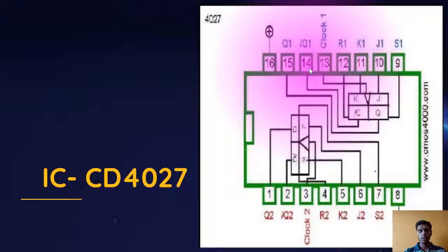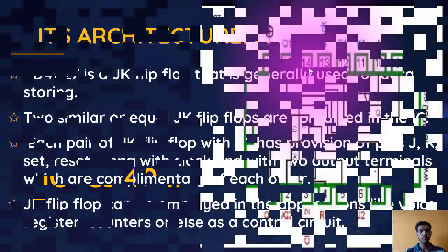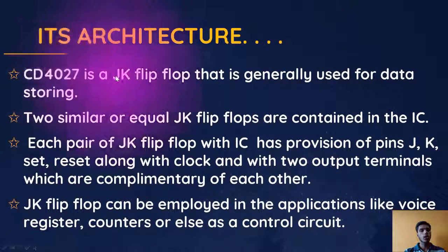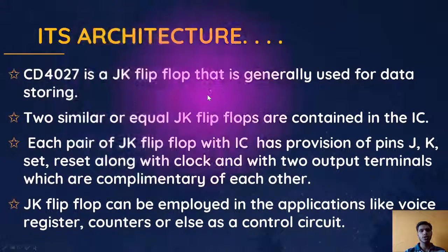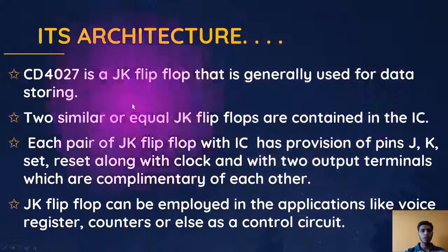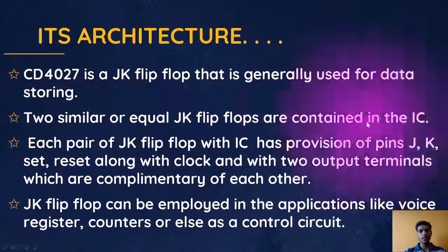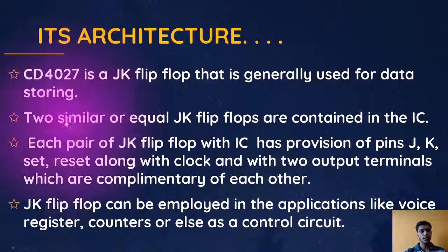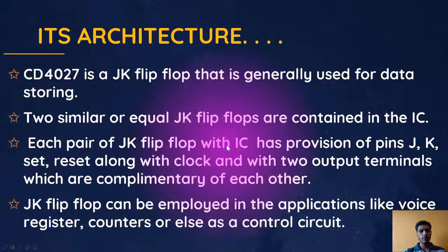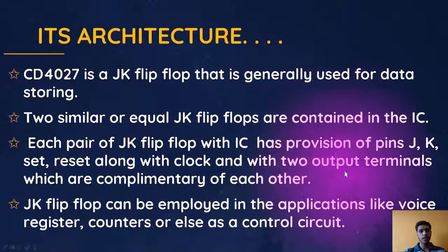Now let us see more about this IC. The CD4027 is a JK flip-flop IC that is generally used for data storing. Two equal JK flip-flops are contained in the IC, as I have told you before. Each JK flip-flop has pins J and K, set, and reset, along with a clock, and two output terminals which are complementary to each other.